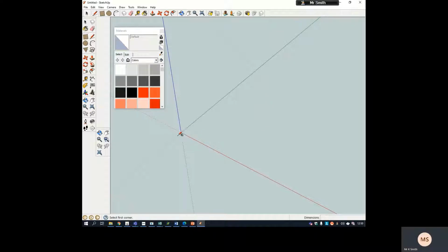And what you do is then you click in what's called the origin point, so you choose the square or the rectangle tool, which is this one here, and then you click in the origin point and you can see it's drawing it along this plane, which means from this axis to this axis. If I just drag out and then I type in the size that I want it to be, make sure num lock is on if you're using the little number keys.